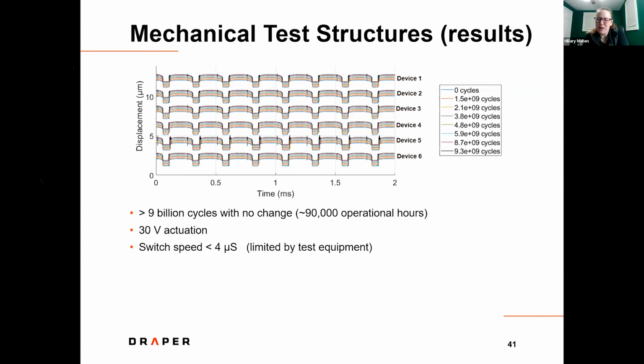Okay. And what is the wavelength bandwidth requirement, narrow or wide, for the Draper method? Well, it's more of what we can accommodate. It obviously can work with narrow. We're going to publish something on that soon. But it's determined by the grating, really. Your grating has a certain bandwidth, depending on what you want to call it, 3 dB or 1 dB. You can estimate the bandwidth from that, but it's 10, 30, 50 depending on what tolerance you can have for loss.